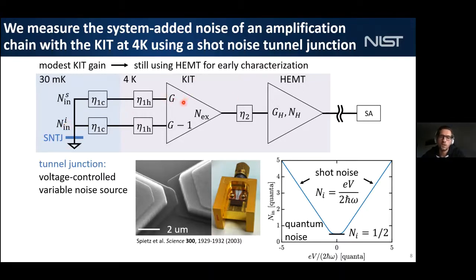This thing can be hot, it doesn't matter. I mean, ideally it doesn't matter. Now, it might increase the excess noise that you would have, but ideally, it doesn't matter. I agree that your technical excess noise might increase, but this is for other reasons that we are actually looking at. For example, maybe the amount of quasi-particles that we have and so on. But this has nothing to do with the thermal. This noise here, the quantum limiting nature, has nothing to do with the thermalization of the device.